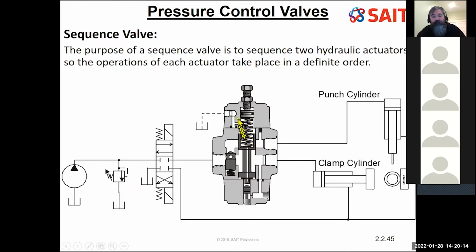Okay, if I didn't have this drain line hooked up, the fluid that would be trapped behind here would be trapped. Okay, it wouldn't be able to move anywhere. So a little bit of fluid can escape through the line. As this moves back, it's going to actually suck in a little bit of fluid back out of the line. So the little bit of fluid there that moves backwards and forwards over the operation doesn't really go anywhere, but it needs to be opened to air.